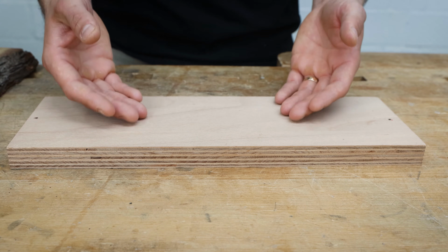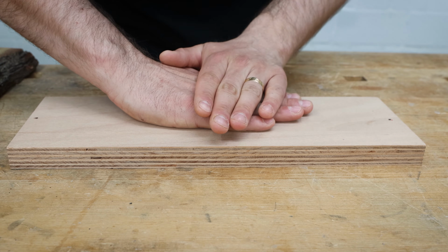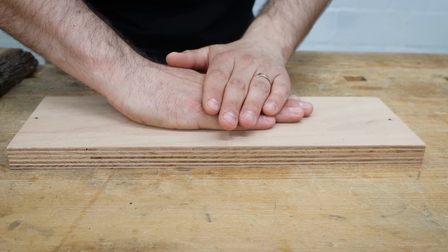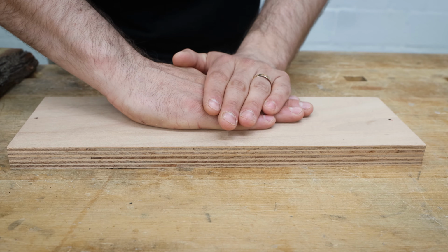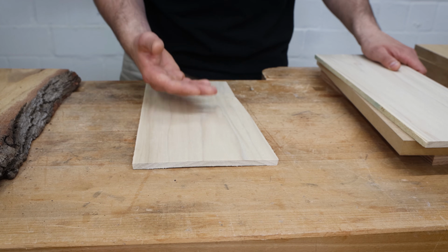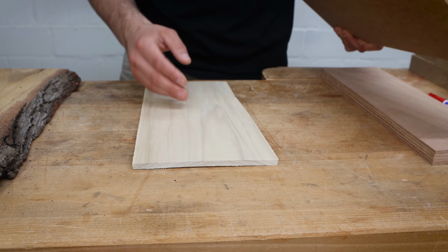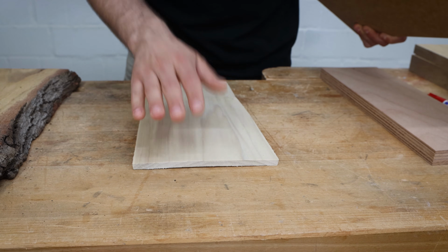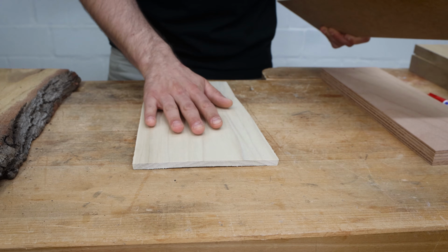The reason why this is still holding up is because these veneer layers are glued together on the whole surface. So they basically lock each other into place, and there cannot happen that much expansion and contraction because each layer is holding the other layer in place. If you need a stable panel of a certain species, you can even make your own plywood, and it's not that complicated. You can make a very simple three-layer plywood by taking a layer of veneer. This is a little bit thicker than a normal veneer, and I would not take this for an actual piece of plywood, but this is just to demonstrate it.